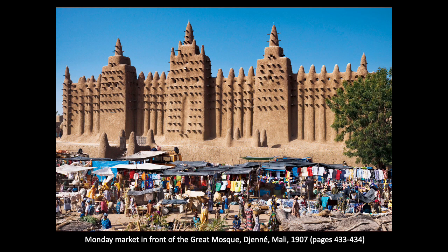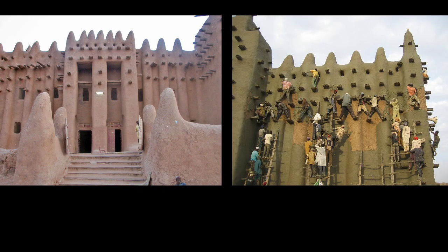A mixture of mud, water, and straw was collected and packed into a mold and then left out in the sun to dry. The dried mud bricks were then stacked to form the structural walls and then covered with a mud plaster to help hold them in place and to give a plastic sculptural quality to the imposing structure. Numerous palmwood beams support the mosque and line the ceiling, giving it a distinctive look, but also serving functional purposes.